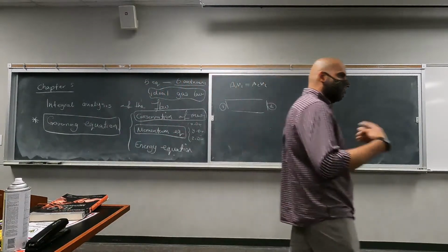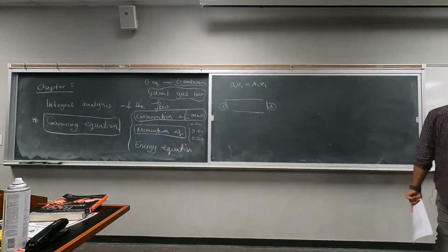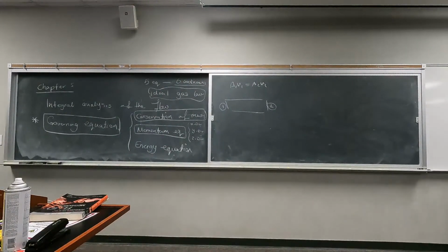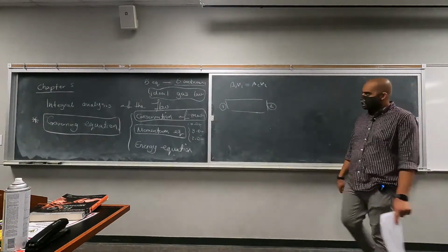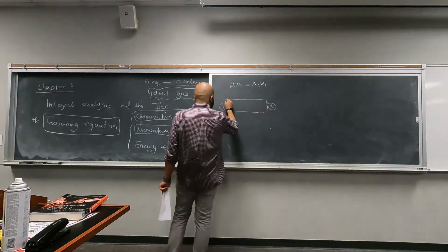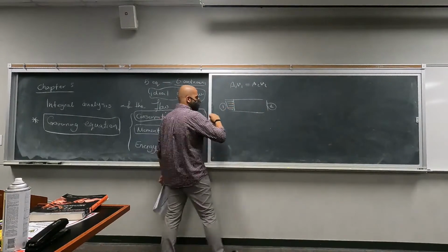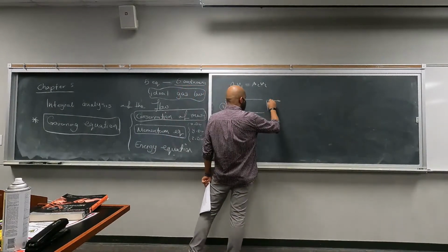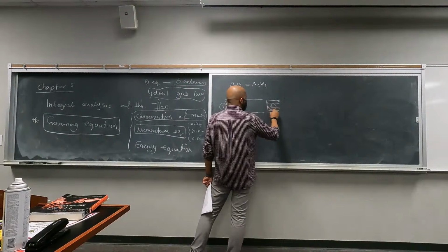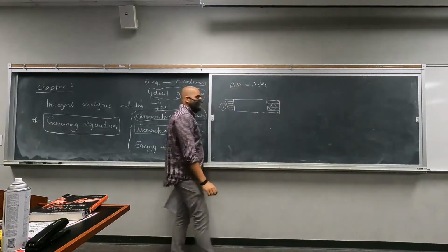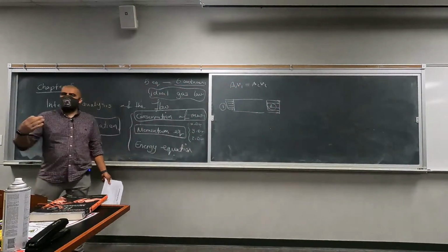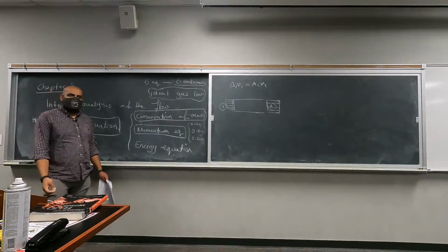So the cross-sectional area of surface 1 multiplied by the velocity at surface 1, if the velocity distribution is uniform, which means the velocity is the same throughout the surface, is equal to the uniform velocity at surface 2 multiplied by the cross-sectional area of surface 2.